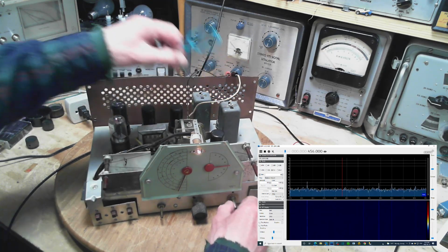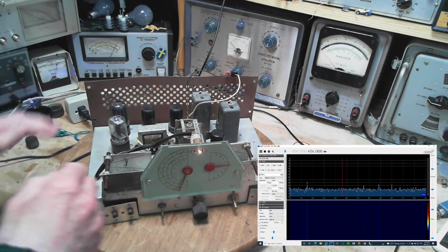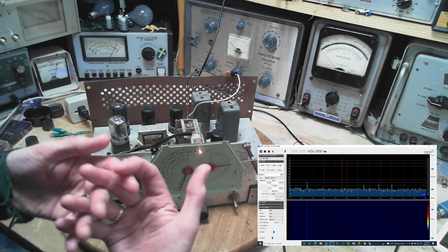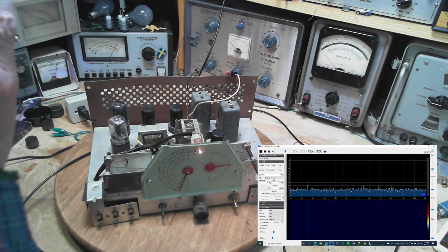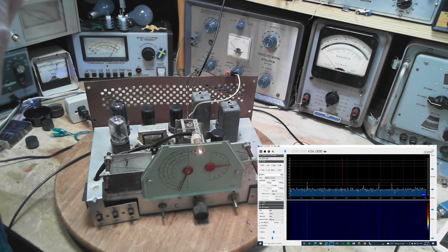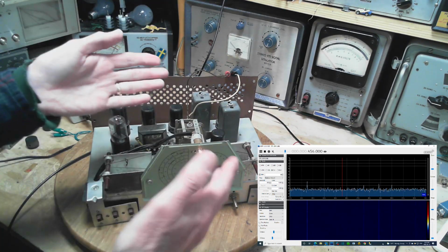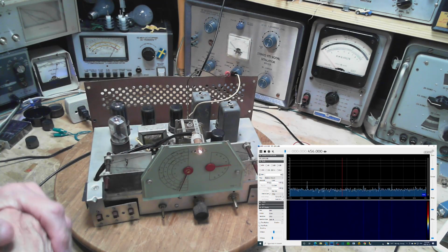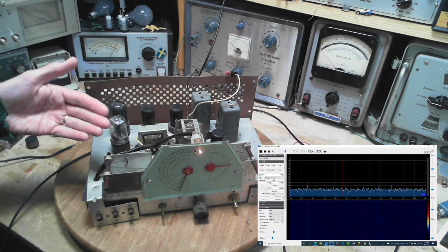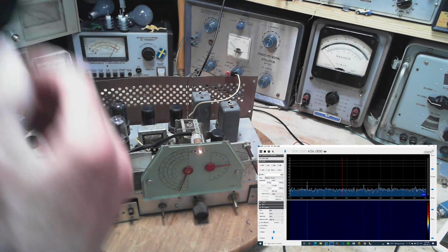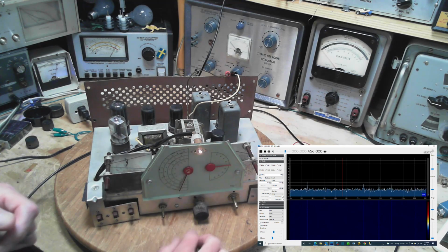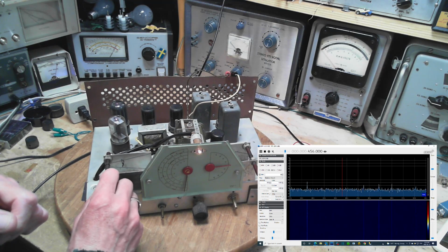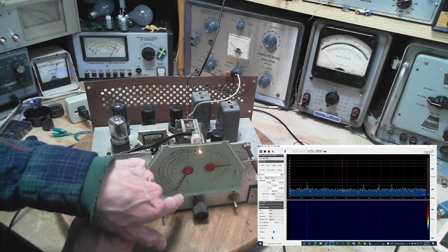So bearing in mind that this is going through a mixer tube, and so these signals that are coming in, stuff is happening in that mixer tube. Could be this sound we're hearing is a bit of a, I don't want to use the word mixture, but I will. Mixture of these two noise signals, one coming in at 450 right from the antenna, and the other one being converted in through the use of the local oscillator. It's just specific to this spot though.